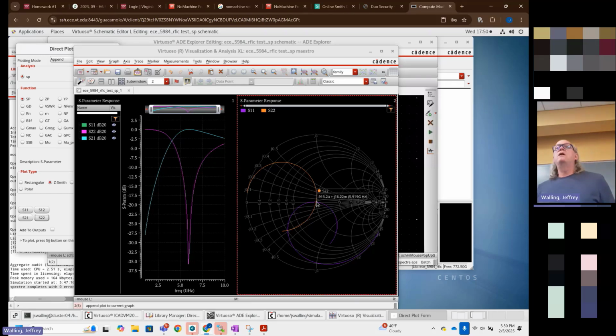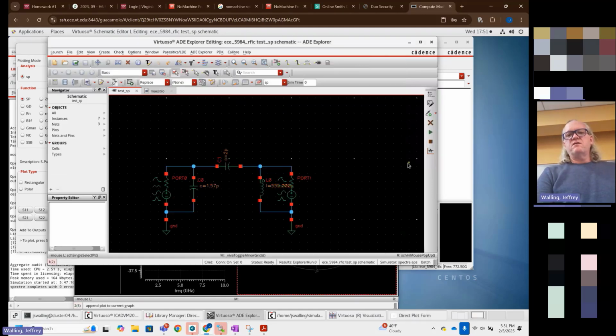So for the network, what if I switch the inductor and capacitor, like the position of the inductors? We'd have to retune all the components in the match, and by the way, it might not be possible for that network to work. I don't think it would, because the capacitor match is a different configuration from the one that you showed. A tapped capacitor match is just a generic term for a matching network where one of my impedances is connected to the center tap between two capacitors.